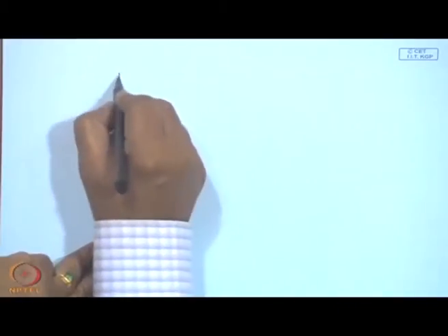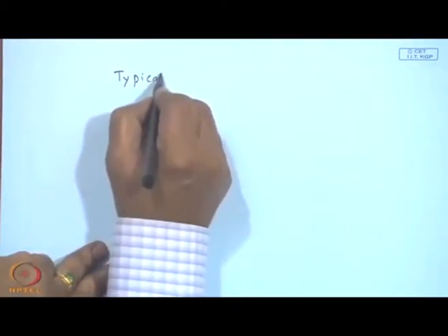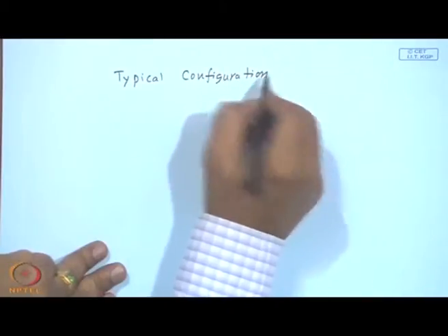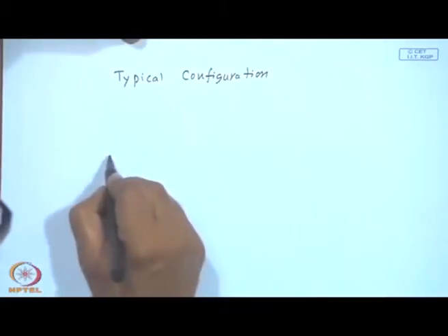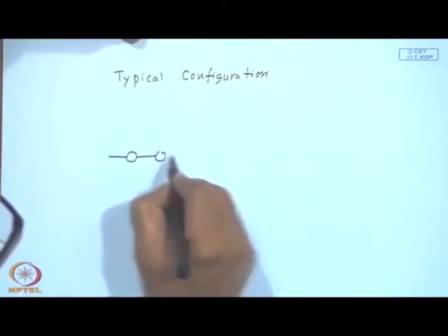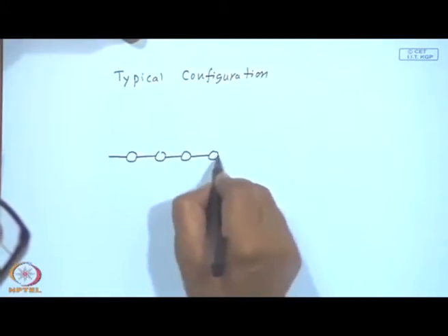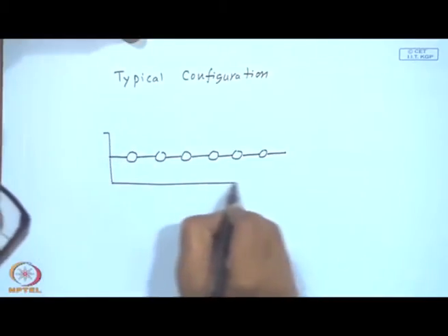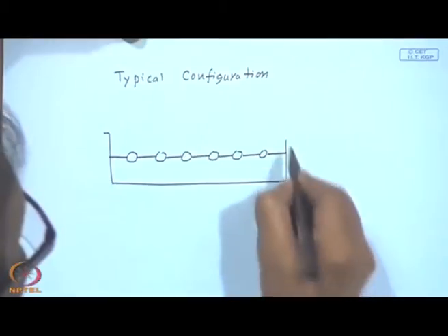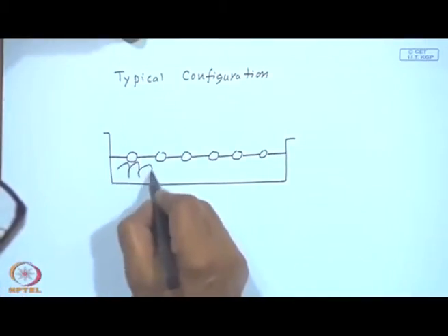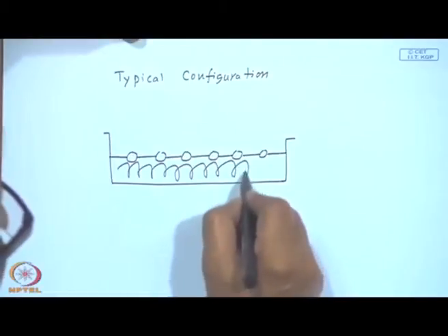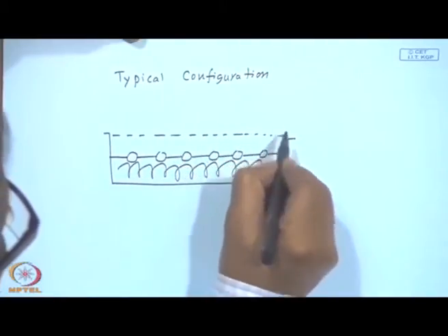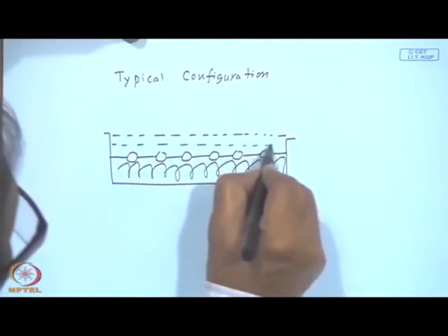So, one typical configuration I shall show for a water heater, which is the most popular fin and tube type of absorber that is kept in a box, and the box is insulated so that conduction from the bottom is reduced, and there will be one or two glass covers.